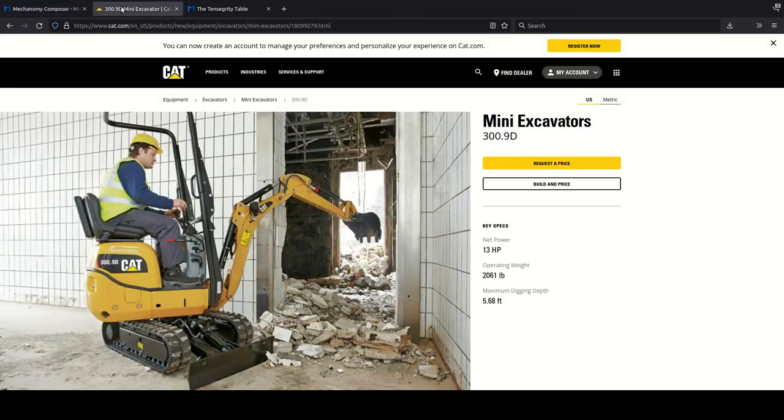So in this model, we're modeling just the excavator arm of this very small cat excavator. We have a revolute joint here at the base. We have one large rigid body. We have a second revolute joint and a rigid body, and then we have a bucket. We're not going to model the hydraulics or the environment that it's interacting with. Hydraulics are doable, the environment is very much harder.